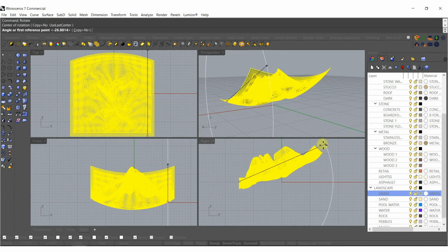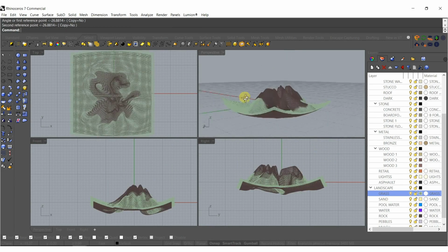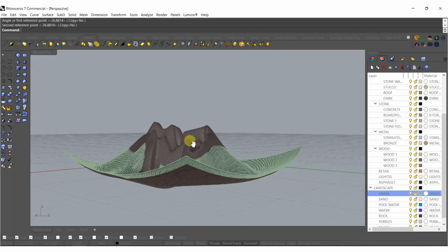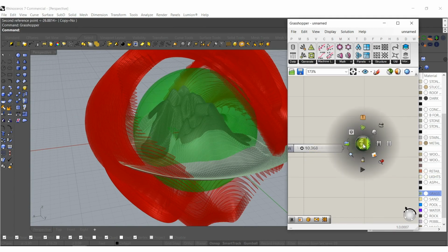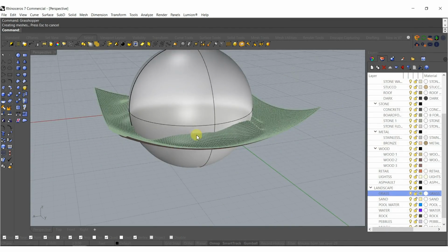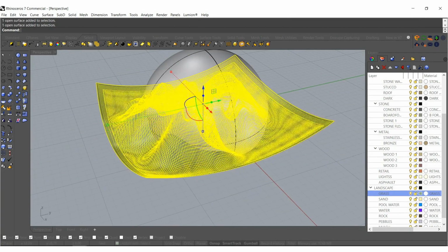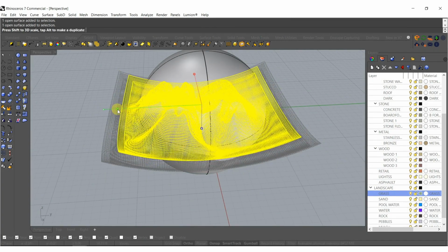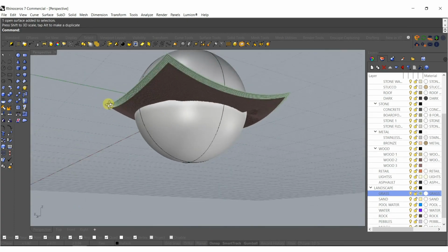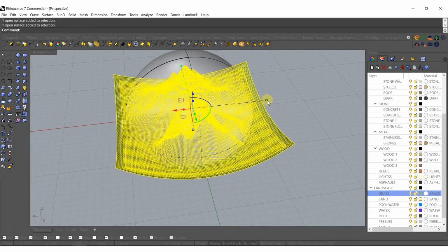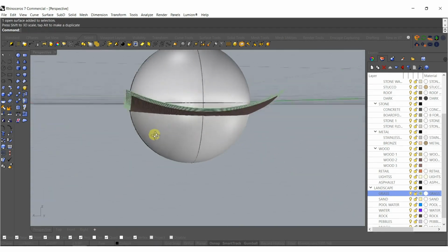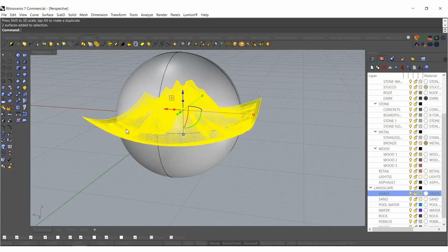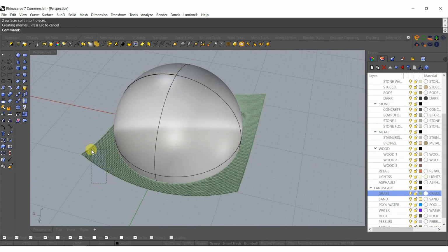Okay, now I'm going to type in Grasshopper. We're going to get that sphere baked out. Looks great. And then we can downsize this just a hair. Try to get the most out of that landscape we just built. Looks good to me. And from here, what I'm going to do is just split this geometry up. And what I want to do next is actually split the sphere there. We're going to take the top half, delete it out, delete out the sides here.